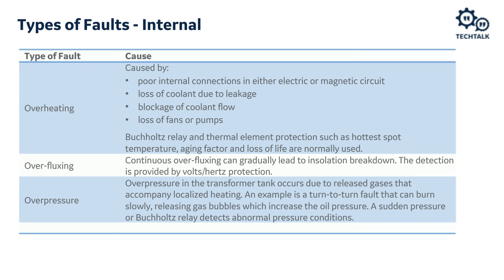So first, we could have overheating. That's a problem that can be caused by poor connections or inadequate cooling of the internal circulating oil, either from a blockage somewhere or loss of fans or pumps, or loss of the actual coolant from an oil leakage. Most commonly, a Buchholz relay is used, and this is an external device independent of our protection relay that essentially detects gas buildup within the oil tank, and it's usually mounted somewhere up near the bladder.